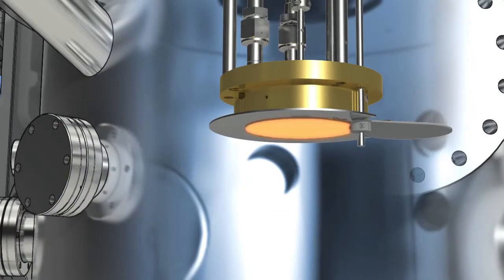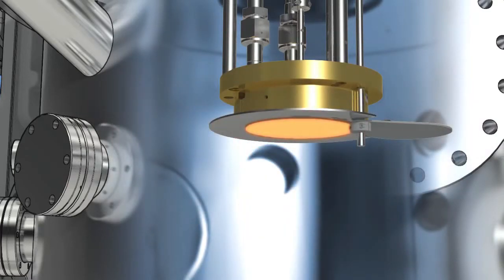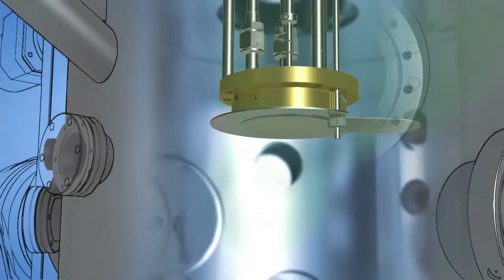Another option offered by PVD Products is applying an RF bias to the substrate surface. This produces a plasma right in front of the wafer that can be used to pre-clean the substrate surface prior to deposition in a background of argon gas, or to conduct reactive film depositions of oxides or nitrides when sputtering or depositing films via PLD. This option does not occupy any of the ports on the back wall of the chamber, leaving them fully available for the other options noted, and thus can be integrated into almost any of our configurations.